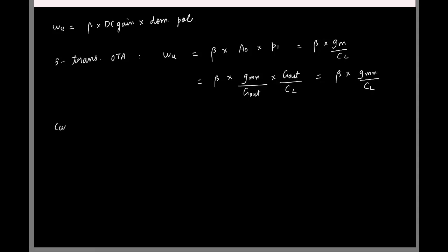So now let us say I take a cascode OTA. So what is this equal to? Correct. Right. So like he's saying, the moment we go to cascode, what changes in the cascode structure? Only the R out changes, right? And here you see the effect of R out is kind of getting cancelled. So here also this is the same thing. Okay.